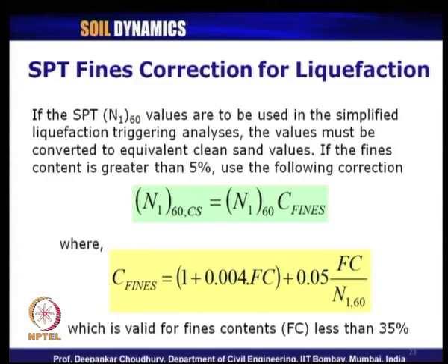If that percent fines in the total amount of your soil, while doing the sieve analysis or gradation study, is greater than 5%, then we need to apply this correction, which is called the equivalent clean sand fines correction. This is the fines correction factor and the corrected value is N160 CS.